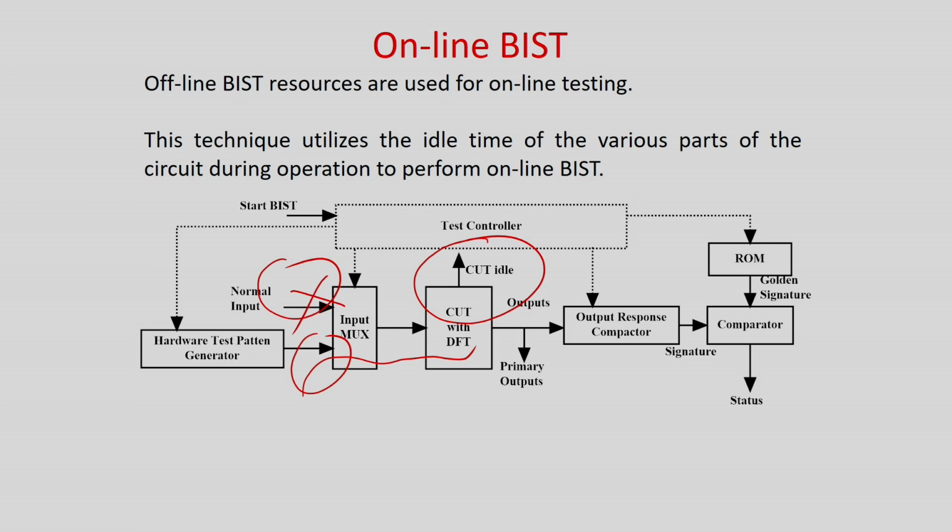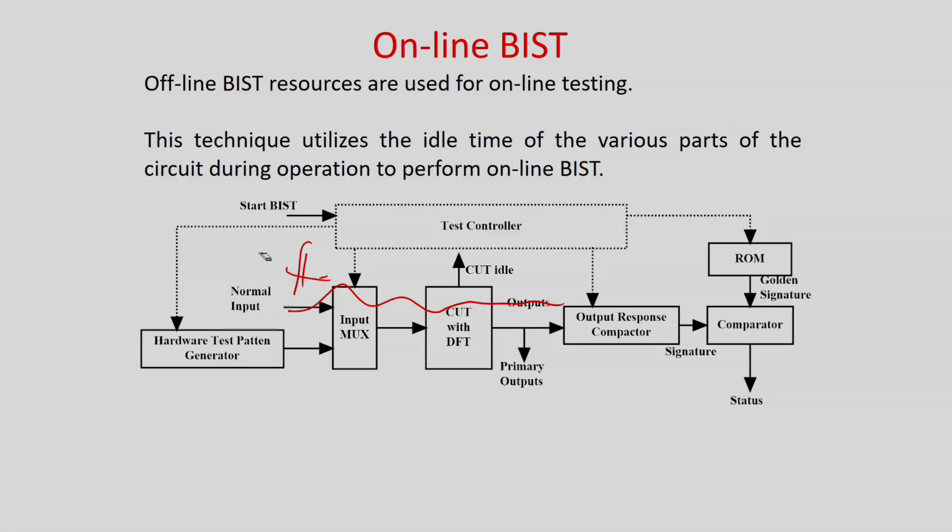But now it is in an online testing mode. In online testing mode, you cannot stop this. You cannot make it stop, because inputs are already coming and the circuit is operating. If you stop the inputs, this no longer remains an online test. But some scientists have thought that it is not always the case that all your circuit modules are operating. They sometimes call these idle modules of the circuit. But with parallelism and pipelining coming into the picture, the idle cycles of circuits are very few. But in general, you know that all parts of the circuit may not operate at all possible times.